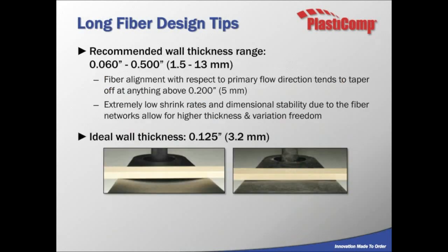People ask me often, what thicknesses do you recommend on this part? Now that's a much tougher question than it sounds. In traditional resins, you obviously want to stay pretty thin, and I'm talking in the range of 100th of an inch. But now, depending on the amount of fiber, the type of resin, the flow length, all of those attributes to the design influence how thin the part can be.